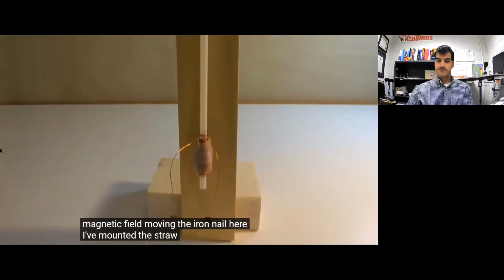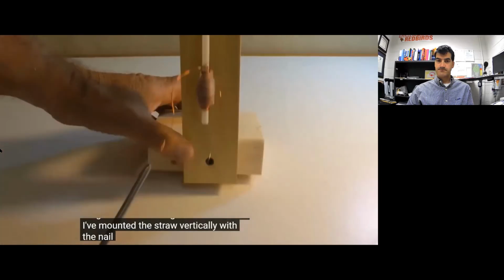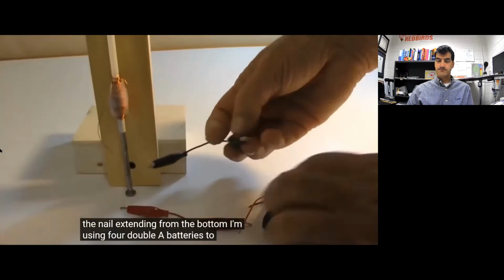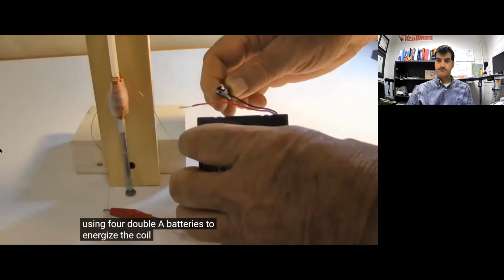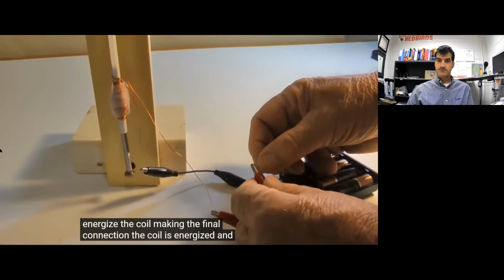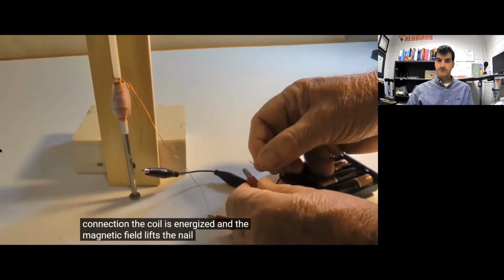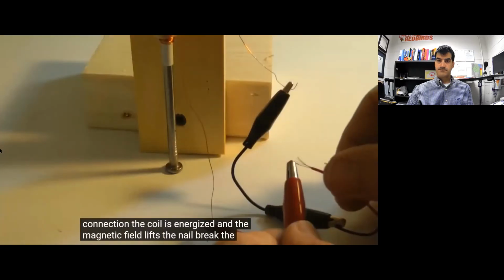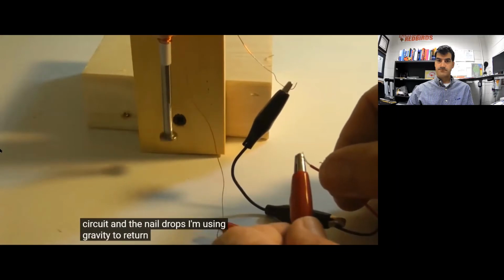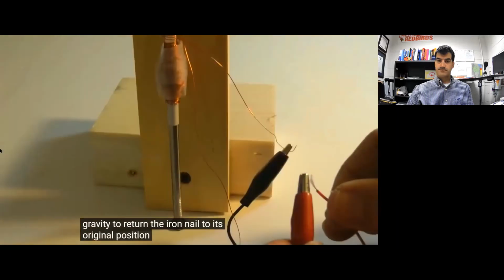Here I've mounted the straw vertically, with the nail extending from the bottom. I'm using 4 AA batteries to energize the coil. Making the final connection, the coil is energized and the magnetic field lifts the nail. Break the circuit and the nail drops. I'm using gravity to return the iron nail to its original position.